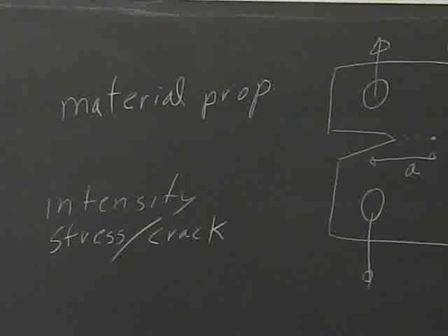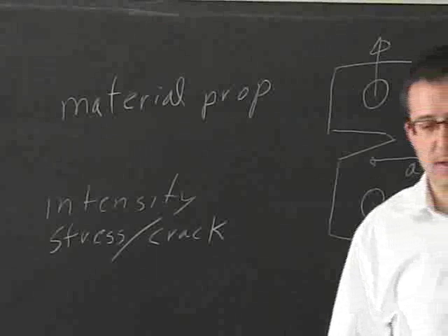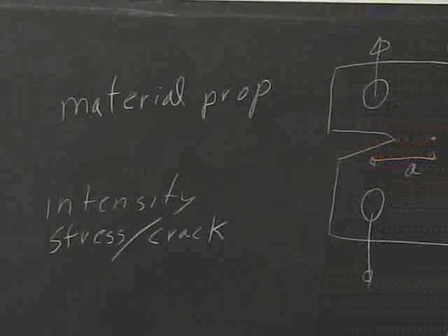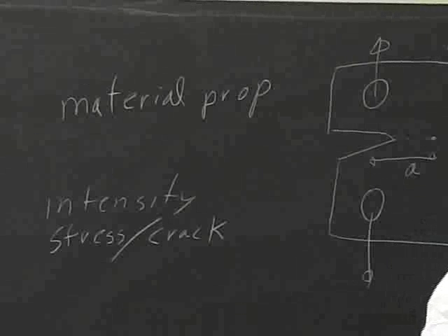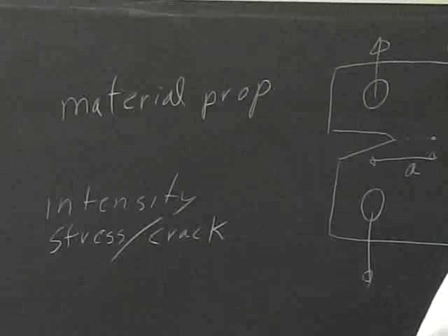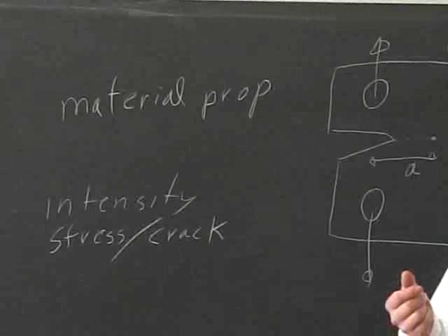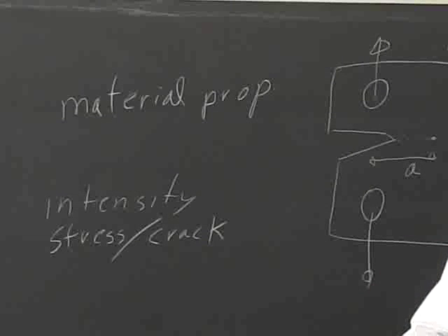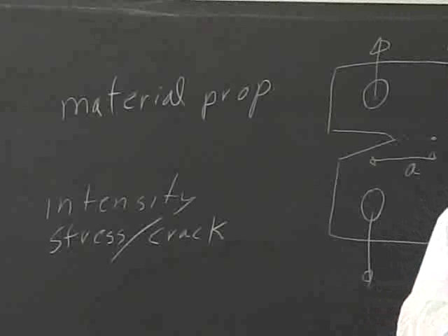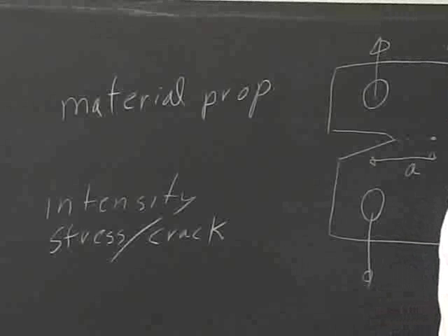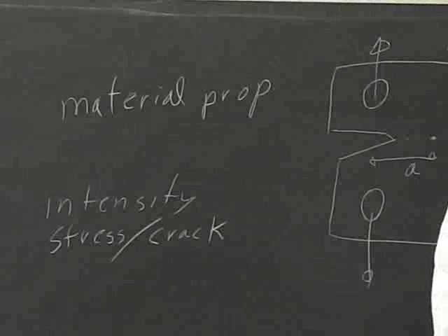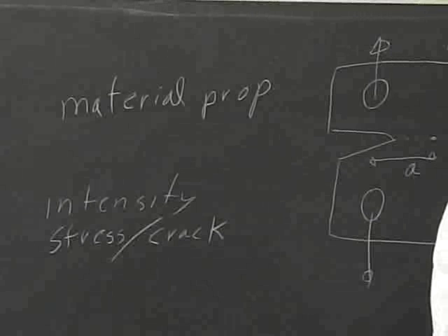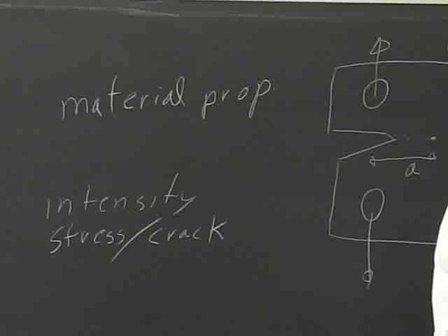So we had somebody do the liquid penetrant, and then we had somebody else do any other type of non-destructive test, eddy current, ultrasonic, any sort of test, especially on welds, and you hope they get in competition. So if somebody finds something and the other doesn't, now the other is like, oh, I really got to work harder next time. I mean, if you really have to be sure there's nothing, then you can't typically rely just on one inspector. Especially when you talk about very large volumes, very large surfaces that essentially always have to be good.